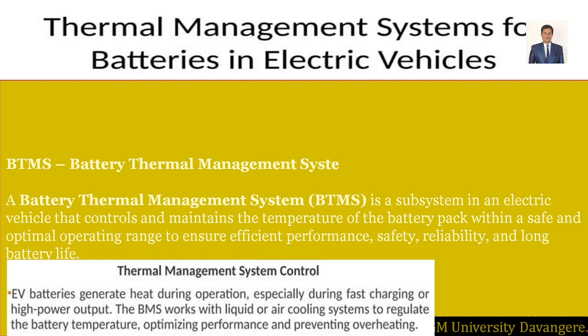It will try to maintain the temperature of the battery pack within a safe and optimal operating range to ensure efficient performance, safety, reliability, and long life of the batteries. You have to think how the batteries can be monitored and what the different temperature ranges are. If it goes below minus 10 degrees, what action do you take?